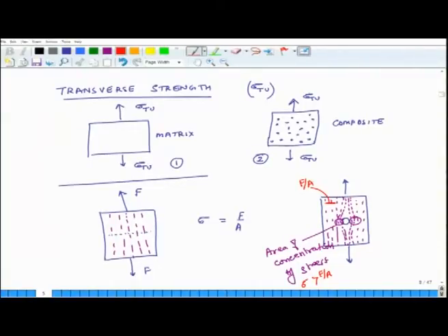So, what that means is that typically this particular situation will have higher peak stresses compared to a pure matrix material, and as a consequence this particular material which has just one single solid inclusion in itself will tend to fail at an earlier level. Now, in case of composites there are several such inclusions in the system.